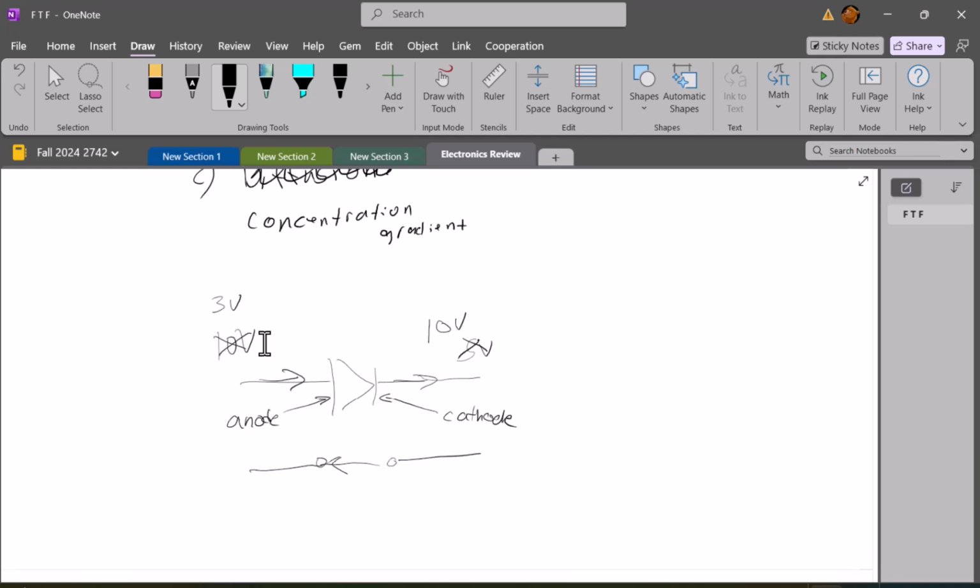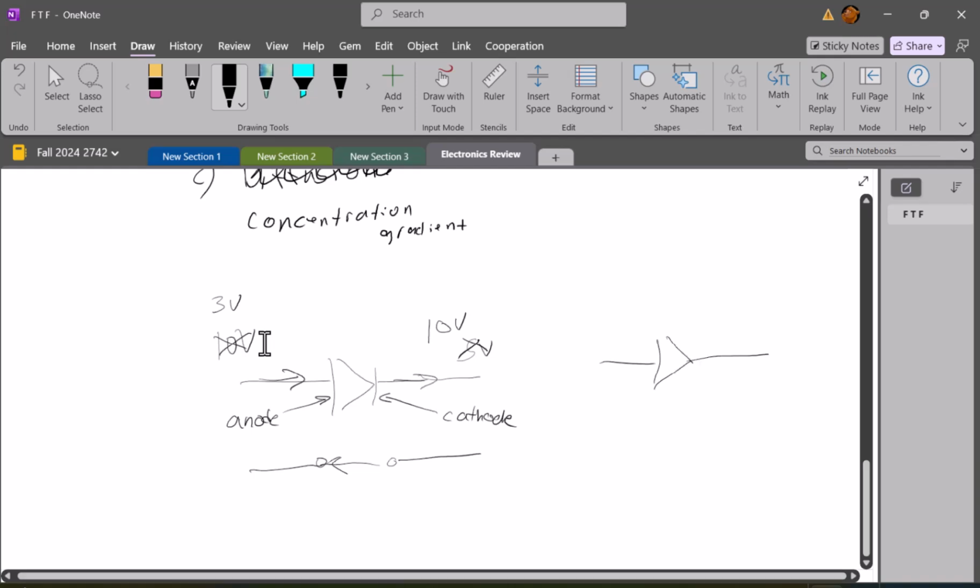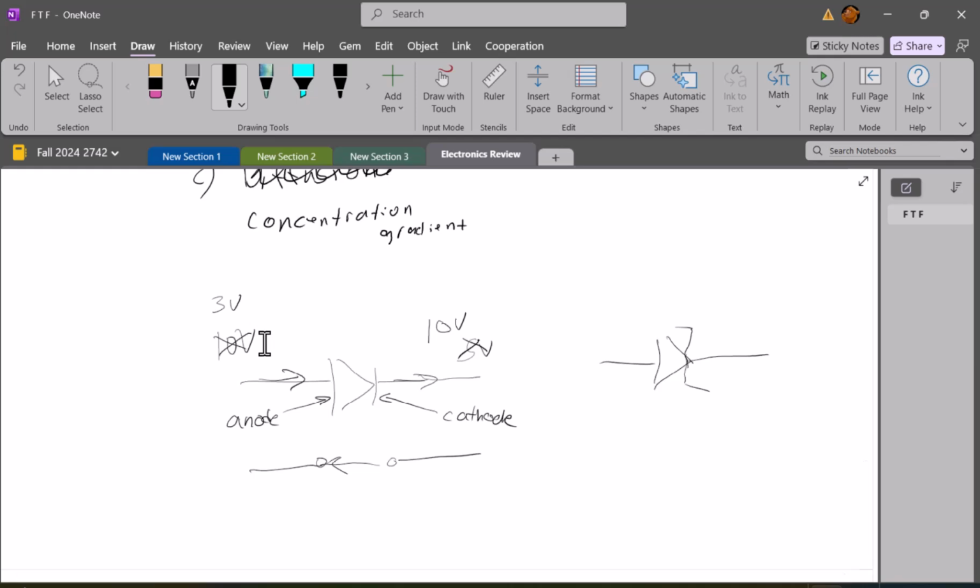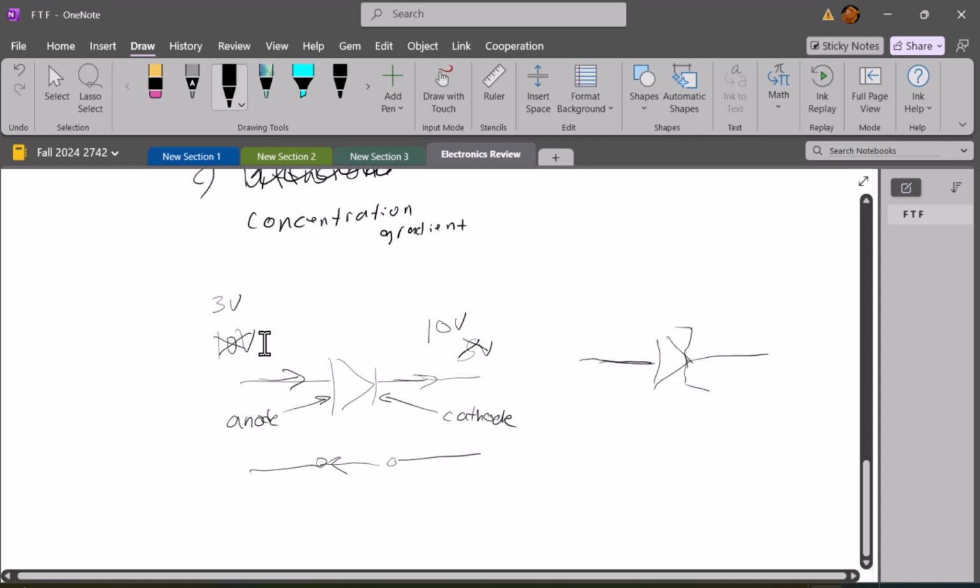Have y'all done Zener diodes? Yes. Okay, so what is a Zener diode? Well, a Zener diode is a diode that is designed to operate in its breakdown region. It operates like a regular diode in this direction, and in the other direction it will also act like a regular diode up to a certain voltage difference. For a Zener diode, it's around 5 or 6.